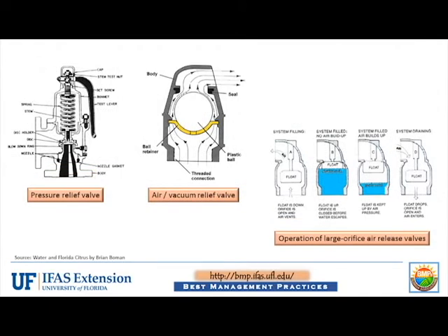Drains and vacuum breakers. Drains and vacuum breakers with an orifice size of at least 3/4 inch in diameter are required. State law requires low-pressure drains to be located on the bottom of the horizontal pipe between the check valve and the water source. It must be located so that the water flow does not drain back to the water source. A vacuum breaker should be installed on the top of the horizontal pipe between the check valve and the irrigation pump and opposite the low-pressure drain.